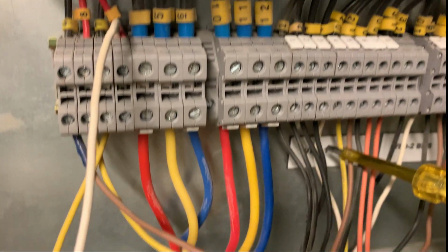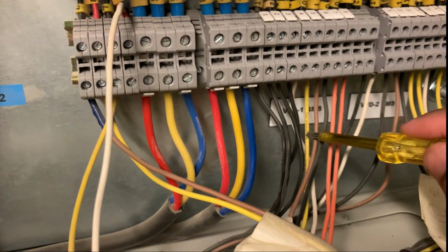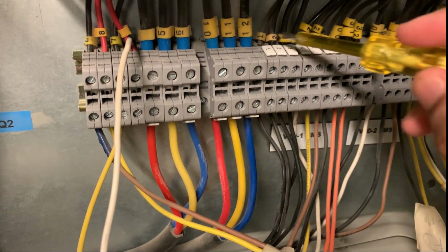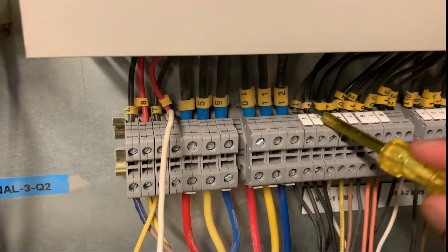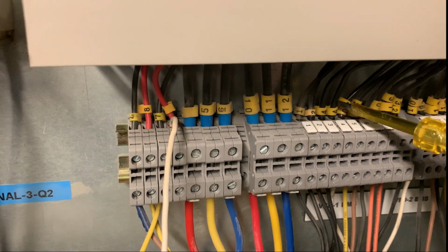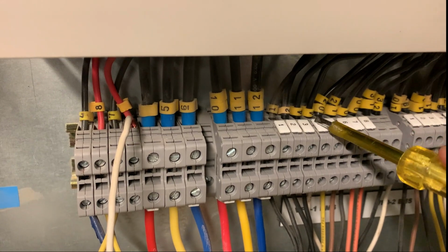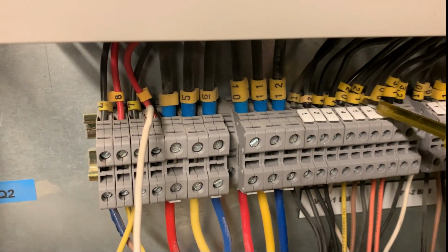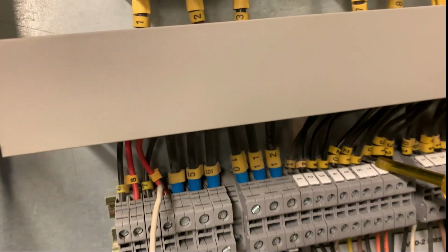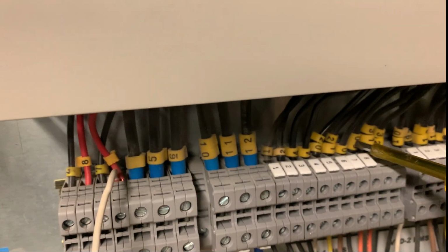So in the BMS we can see whether our VFD or our motor has tripped or not. So this 1, 2 is for command purpose. This 4, 4, I will explain later, and this 20 and 21 is used for the trip status, and this 0 and 00 are for the run status.